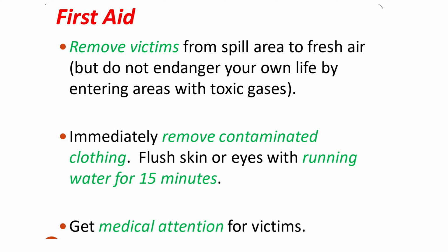First aid. Remove victims from spill area to fresh air, but do not endanger your own life by entering areas with toxic gases. Immediately remove contaminated clothing. Flush skin or eyes with running water for 15 minutes. Get medical attention for victims.